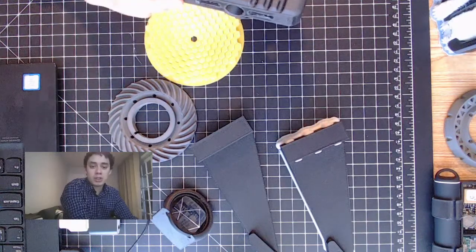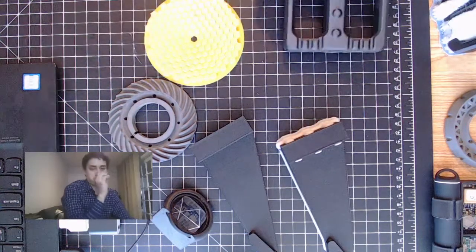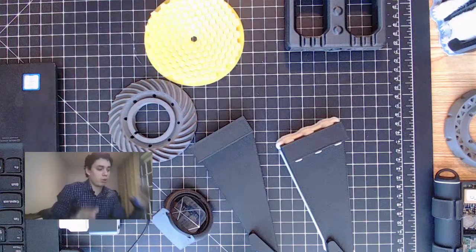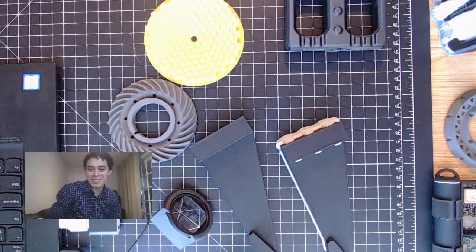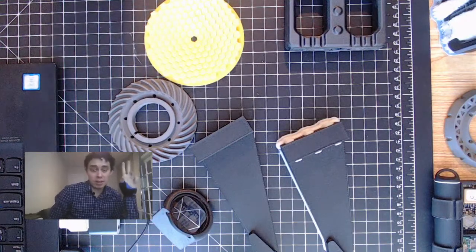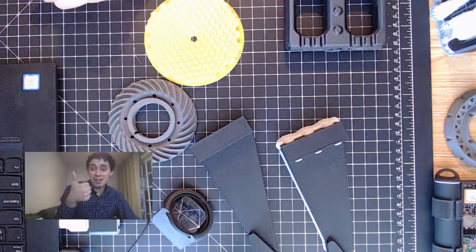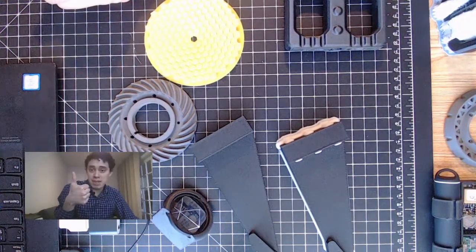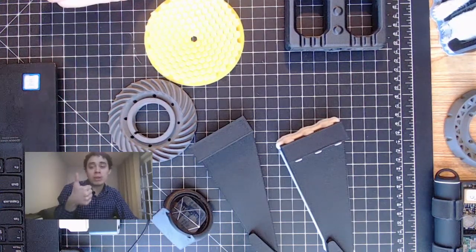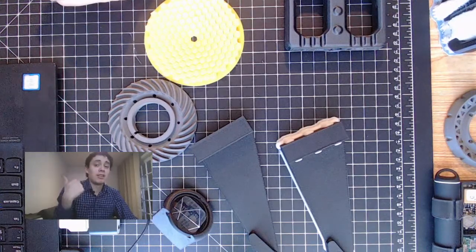What should I consider for optimal results? TLDR, really quick, the overarching takeaway here is going to be three things. First of all, is your part withstanding a force or not? Try to make your layers perpendicular to the force being applied. Second consideration, materials and time.